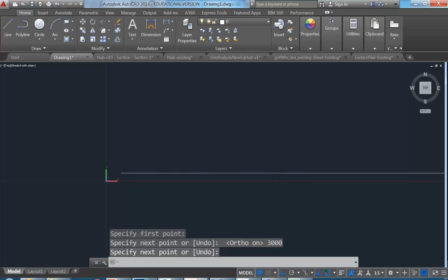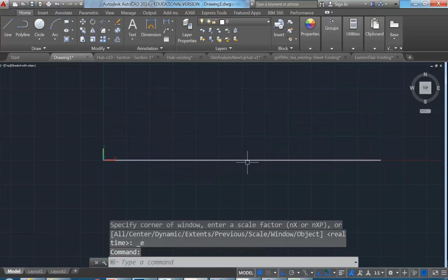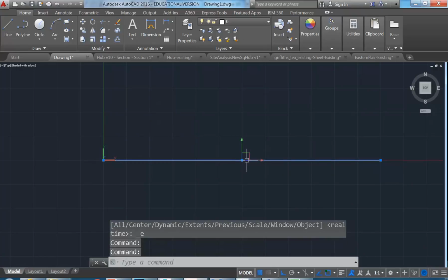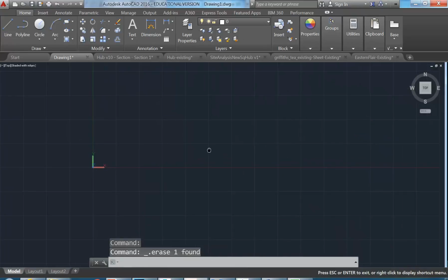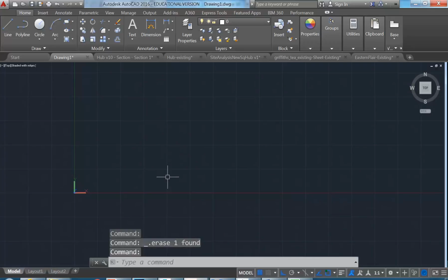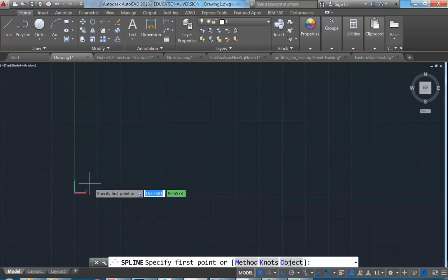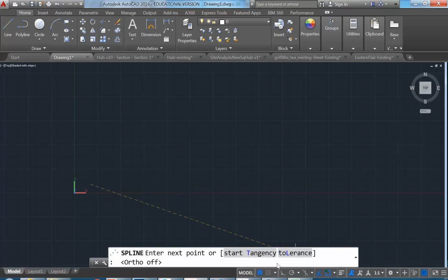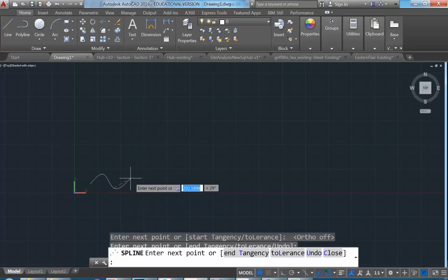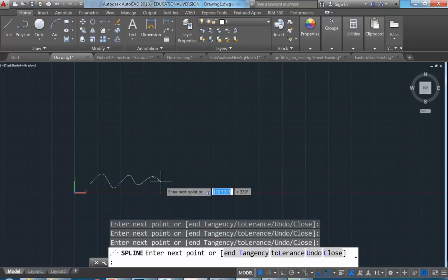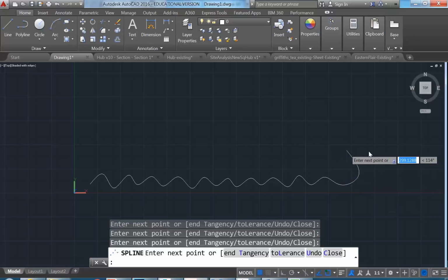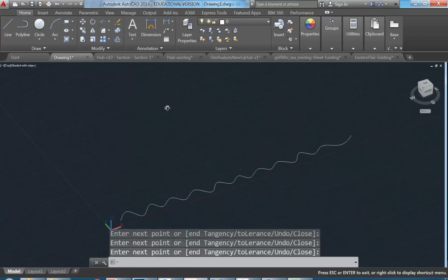So this might help you in AutoCAD as well. If you just draw something like a line that's roughly the size of the thing you're trying to make, that'll give you a view. I just drew a line that was 3 meters long and then zoomed to fit that in my view. And now when I draw my shape, I don't need to be too fussy about the measurements, but I know roughly how big it is. So before, I thought I had the view still set up from what I'd done earlier, but it was zoomed right in down to the scale of about 1 millimeter. Okay, so there we are.